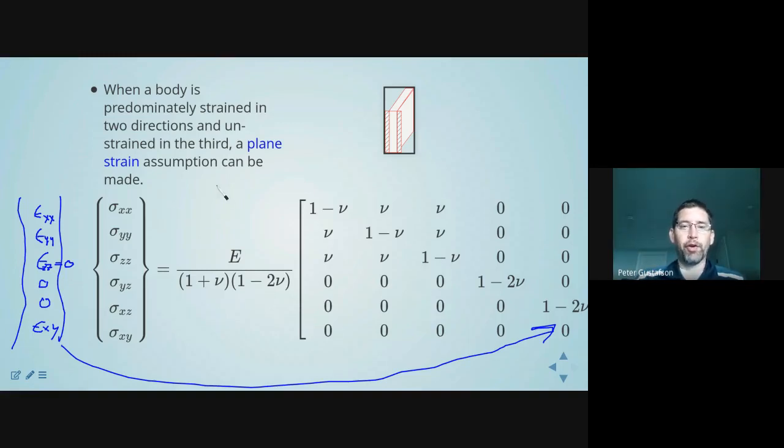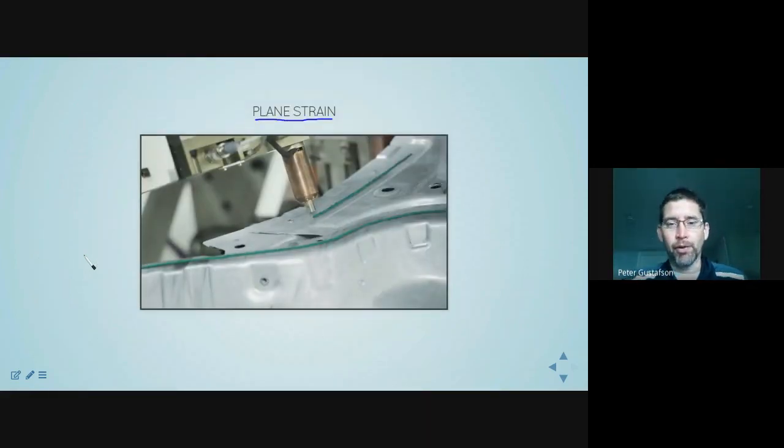And now in this circumstance, you might ask, well, when does this circumstance arise? Why in the world would you ever have a circumstance where the out-of-plane displacement and strain are constrained? Okay, it turns out that that actually does happen with some regularity, and one example is this image that I'm showing you here. So it's becoming more common in the aerospace world to actually use adhesives to bond things together rather than fasteners. It has some benefits: improved load transfer, less stress concentration, lighter weight, and therefore, because of all those things, often a longer life.